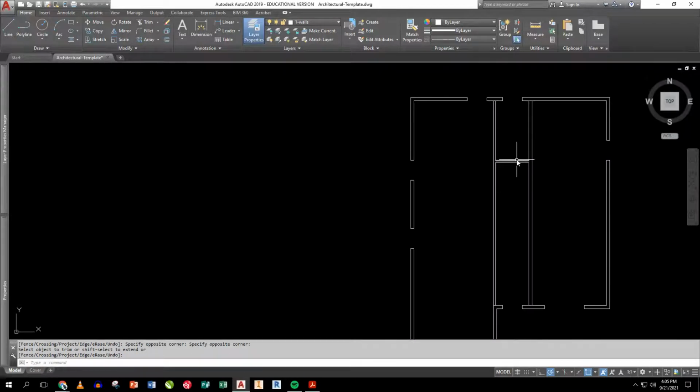There is my bathroom here. Now, I do have an issue with this. A normal bathtub fits inside a 5.0 bathroom, and that's what I would normally do. This will very likely, the way it's drawn, if I don't have a special bathtub, actually have about a 4-inch gap right here on one edge.